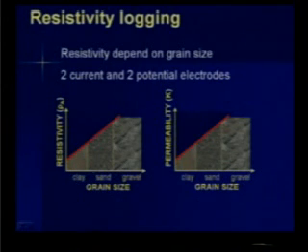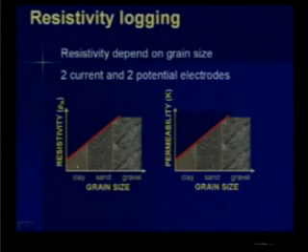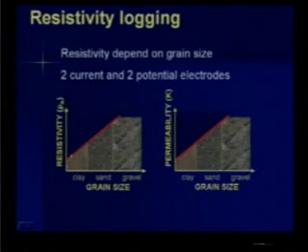Generally, the resistivity of the formation depends on the grain size. Coarser the grain size, higher will be the resistivity. Similarly, permeability of the formation will also increase with higher resistivity, because when the grain size is higher, the porosity will be considerably less, due to which the amount of water present in the coarse grained formation will be less than that present in the clayey formation. Because more water is there in clayey formation, it offers less resistivity.